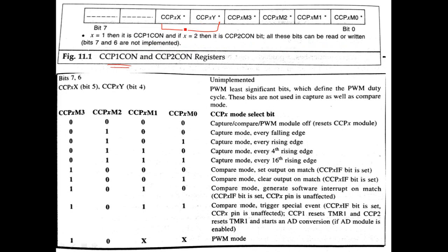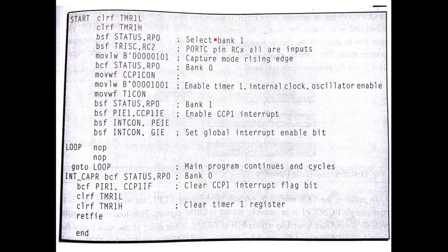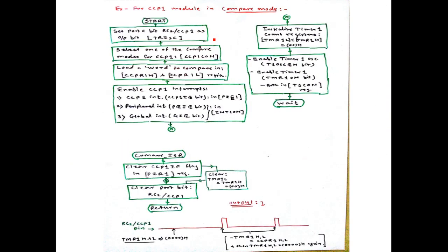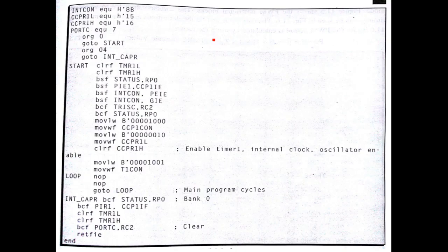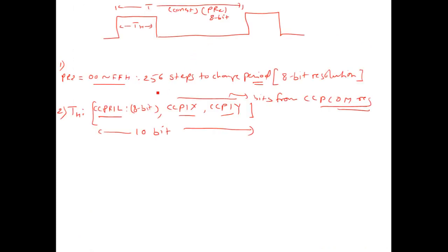These are typically used in PWM mode. You may put here 00, maybe 01, maybe 10 or 11. Those bits are appended to the 8-bit count in the CCPRL register, so as to obtain the total count to be of 10 bits.